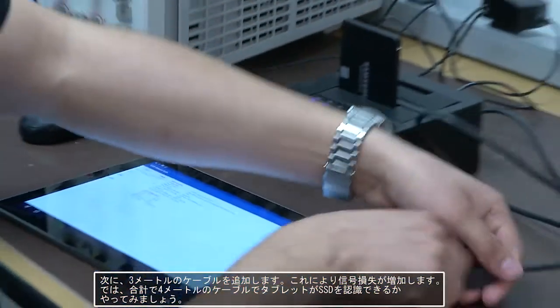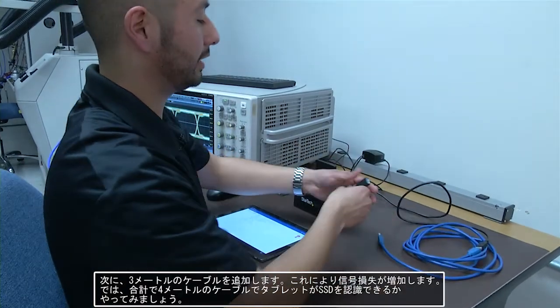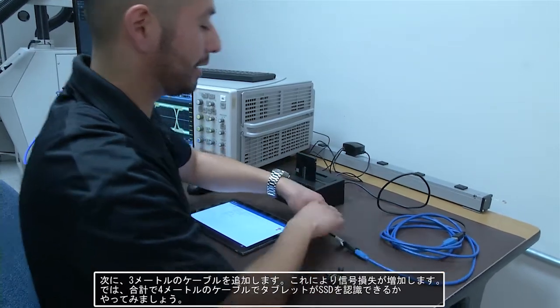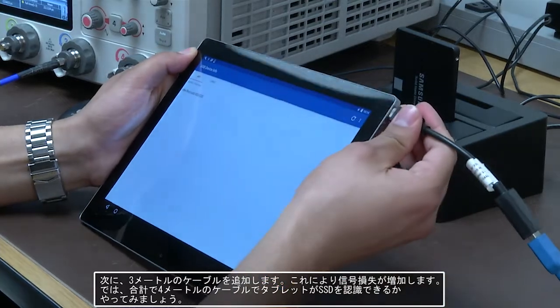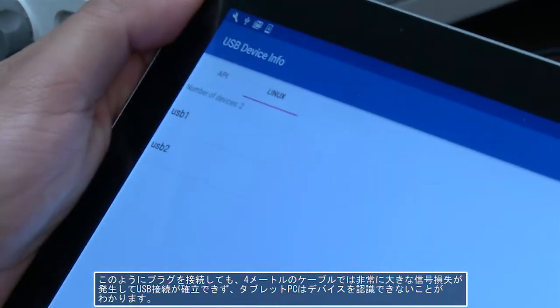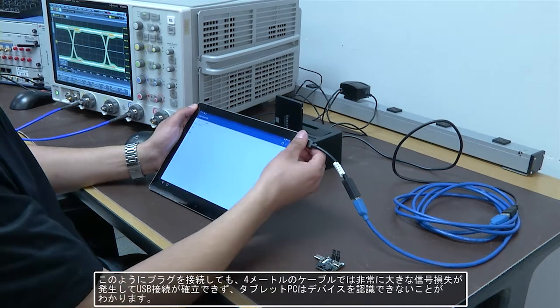Now I'm going to add 3 meters of cable to the system. By doing this, I'm tripling the amount of losses going through the system. So let's see if the tablet can recognize the solid-state drive after this 4 meters of cable. Once I plug it in, you can see that the USB connection was immediately dropped due to the fact that 4 meters of cable has tremendous losses. The tablet was not able to recognize it.